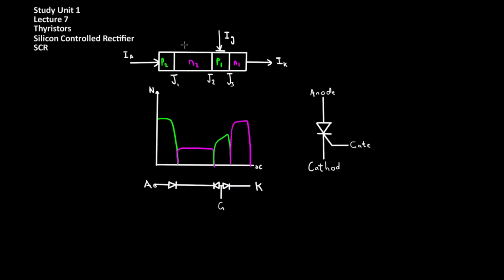The basic silicon-controlled rectifier shown here is a thyristor which has 4 doping regions and 3 junctions. A general property of thyristors is that they have a latched on state and a stable off state. For the silicon-controlled rectifier, or SCR, shown, the behavior of the device is determined by the doping profiles as well as the width of the various doping regions in the device. Characteristic of thyristors, there is an anode, a cathode, and a gate.